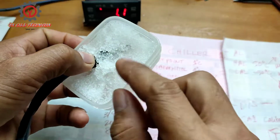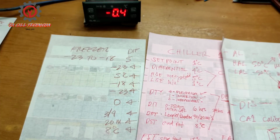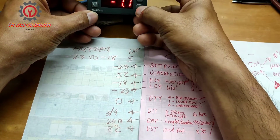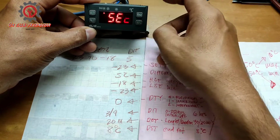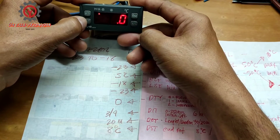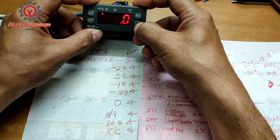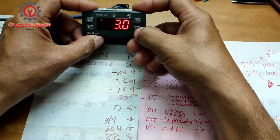Here, just immerse it. Okay, now let's proceed to the set point, guys. To change the set point, just press the set button here for 1 second, then release, then press set again, and we're gonna change that one to... okay, it cannot, so press set again, skip, long press the set button here.